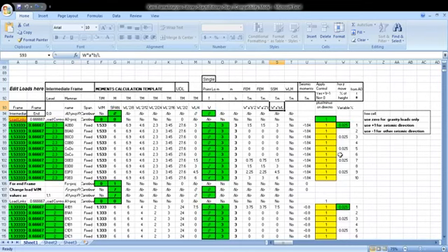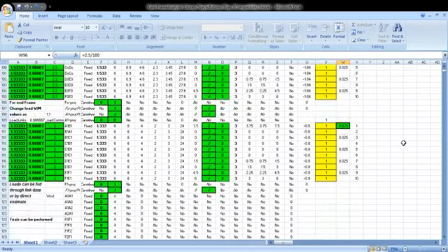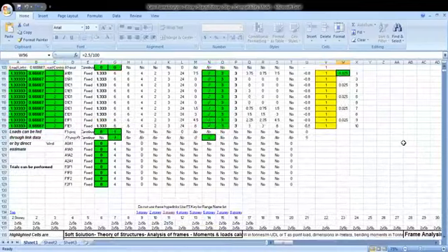And this is seismic, where the control can be 1 or 0. If you make it 0, it should not apply, and if you make it 1, it will apply. And this horizontal force we have taken as 25%. It can be different, for example 15%. You can take it like this also, and everything changes. Use 0 for gravity loads only, use +1 for one seismic direction, use -1 for the other seismic direction. This links to that calculation area.